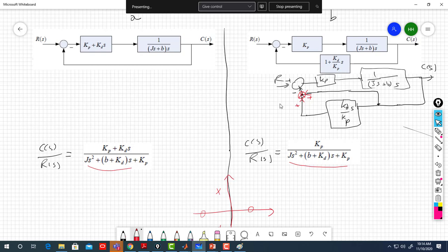In the library, what they are doing is adding a filter to the derivative term to reduce the noise effect of the derivative controller. But they don't use rate feedback control. Okay? So if you are programmable, you're able to do your own function which suits your needs, instead of being just a user limited by the function provided by others.